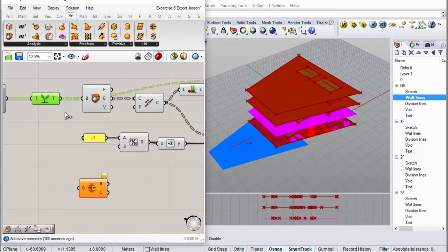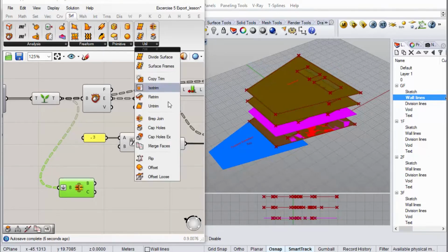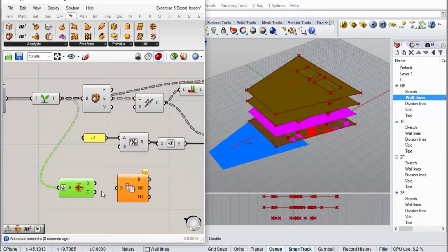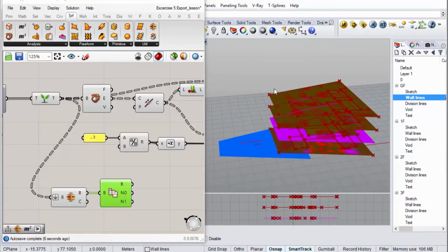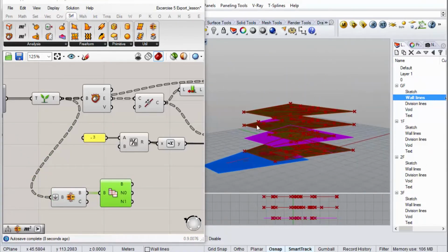The ones that can be joined up will be joined up. That's why we have to flatten it, so that they're all operating on the same branch. Then, just to make this a bit neater, we're going to merge the resulting faces to get one clean, uninterrupted surface.